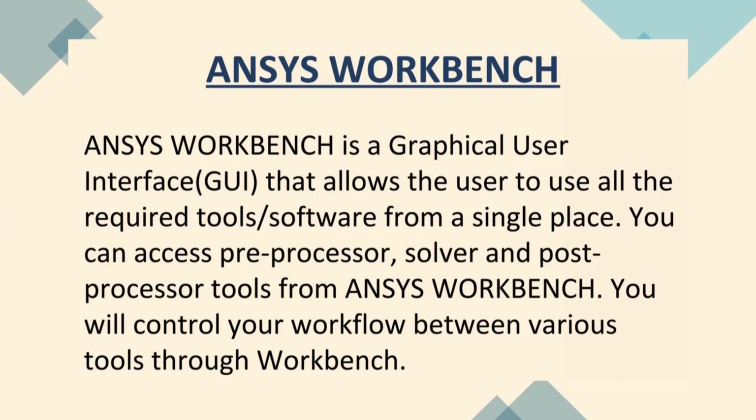You just give all the boundary names, okay, and come back and then go to Fluent. Fluent can automatically take the mesh file from there. You don't need to do anything. And if you want to do some optimization, you can also do the optimization in there. You just need to set up which parameter you want to optimize. So just mention the parameters, and that can actually optimize for you.